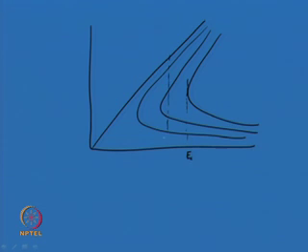If this was the original energy at section 1 1, y 1 and this is E 1, then at section 2 2 the minimum energy possible is E c, because this is the curve for that particular cross section q by b. This is the available curve, and the minimum energy in that curve is at this location.